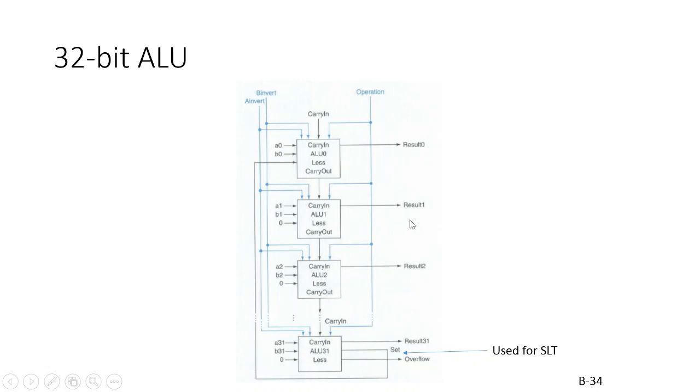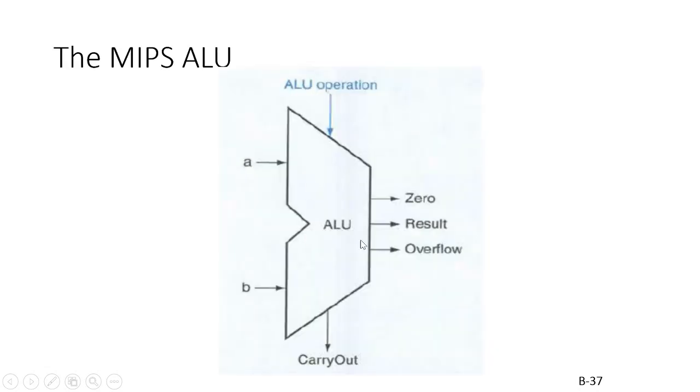Well, when we're doing ALU operations, what are the commands we usually deal with? We're dealing with AND, OR, addition. We already talked about inversion, so we get subtraction out of that, inverting either A or B and doing addition. And then we can get the carry out of that based on what we've talked about so far.